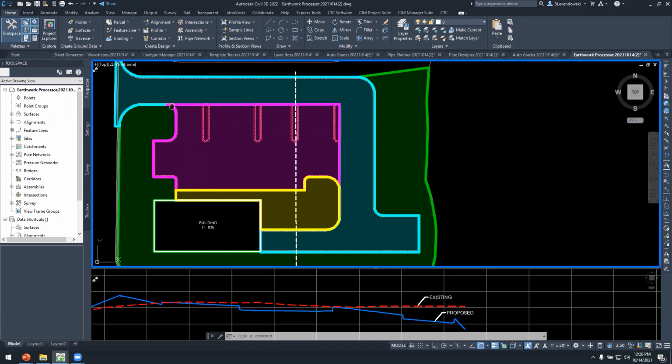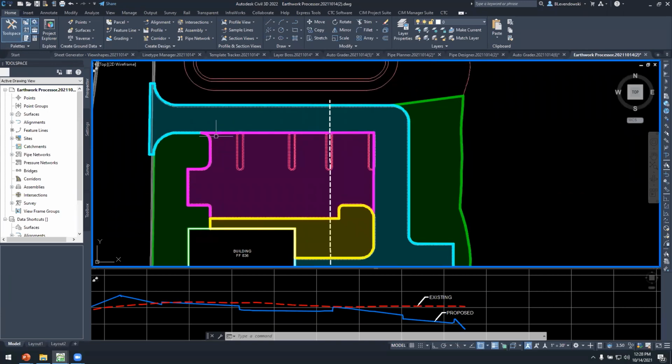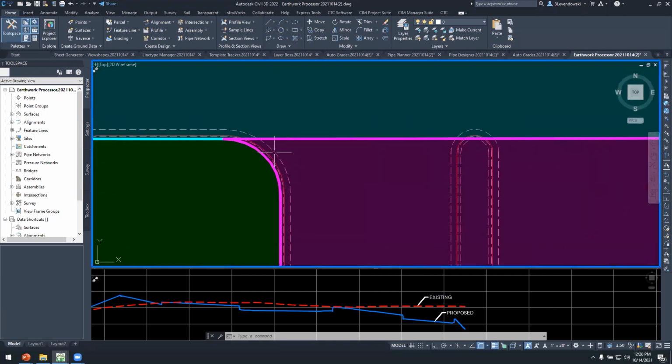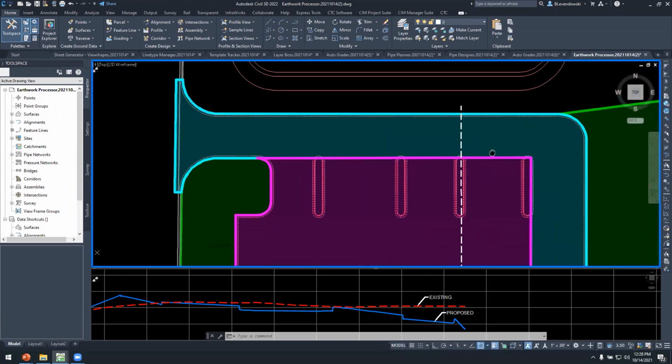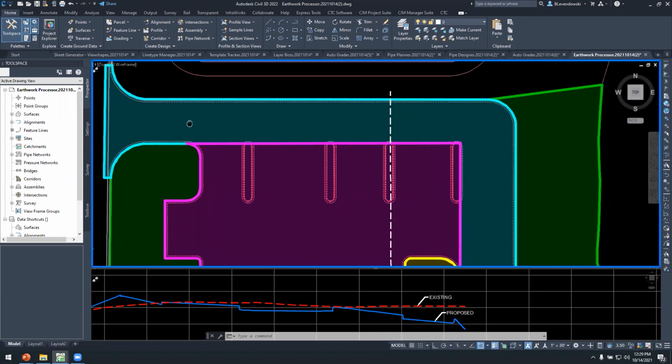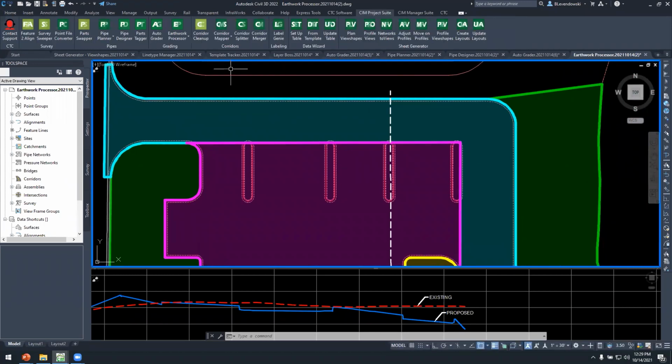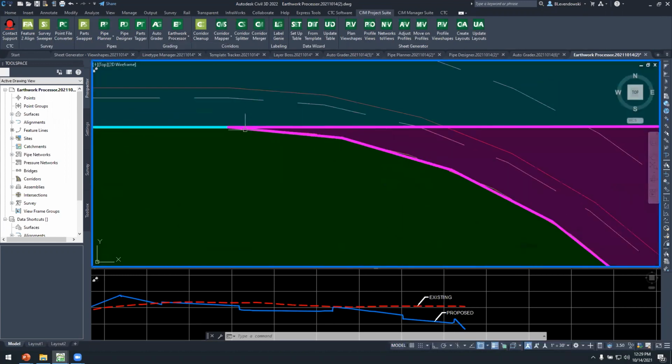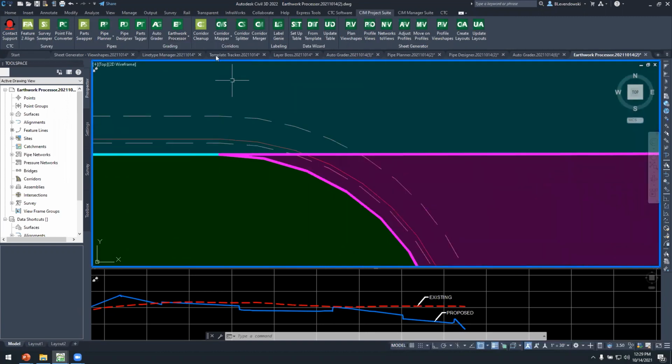So Earthwork Processor, I've got a finished grade, an existing surface, and then I've drawn some polylines that represent these different subgrade depths or different pavement types or hold down depths. And we've got a tool. I'm going to start off with kind of a little subcommand it has. One of the requirements with these different regions is that they're not overlapping. Yet when you're using, perhaps, the boundary command or something, they might be overlapping.